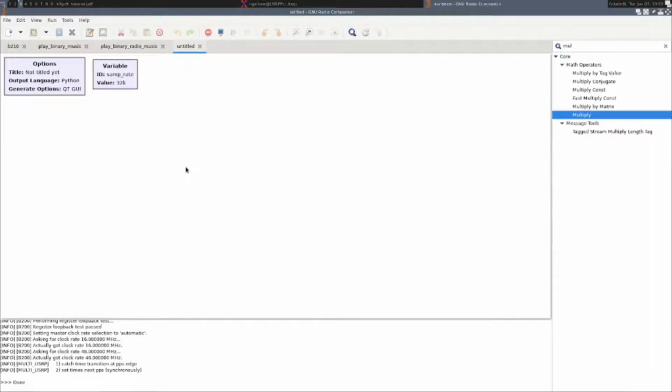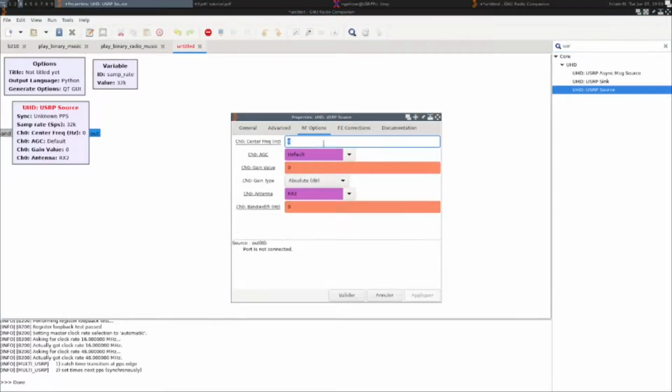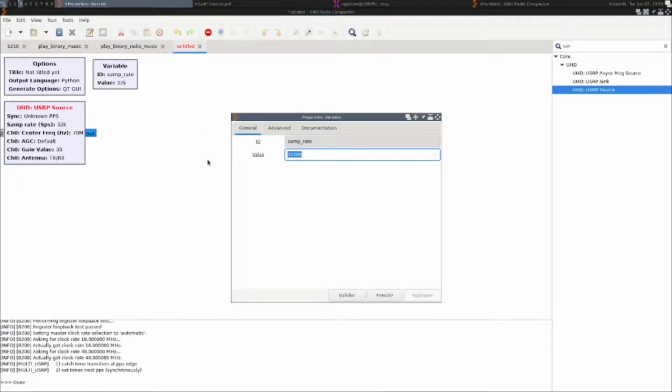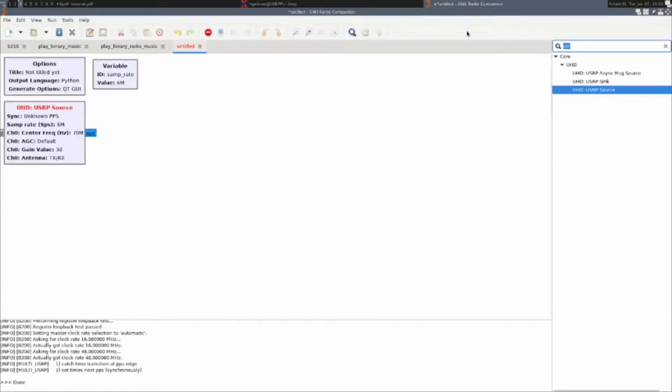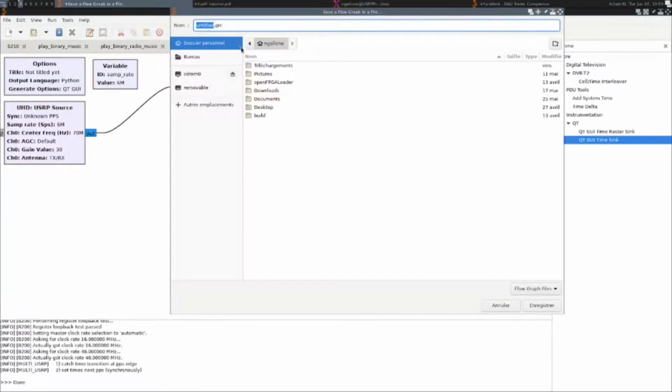So we start with a clean sheet, and the first thing we do is we search for the USRP which represents the B210 software-defined radio receiver. We double-click to set the carrier frequency. We set an educated guess of 30 dB gain, and we go on the TX-RX input. So we have a transmission at 2.5 megabit per second, so 32 kilosample per second is well below the necessary bandwidth. Let's say we take something like 6 megahertz bandwidth, and we first try to assess the amplitude of a signal that we receive. Is the gain that we selected reasonable with respect to the attenuation that we included on